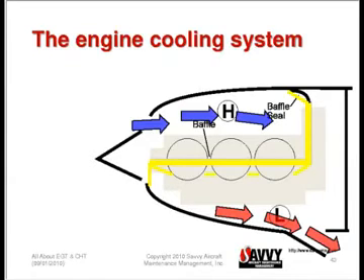And in addition to those baffles, we have to have a series of what are called intercylinder baffles, little plates that sit below and between the adjacent pair of cylinders and so on, so that the air can't just come down between the cylinders. It has to actually wrap around and go through the cooling fins, because if it was allowed to simply go down vertically between the gaps between the cylinders, it wouldn't be performing a cooling function.